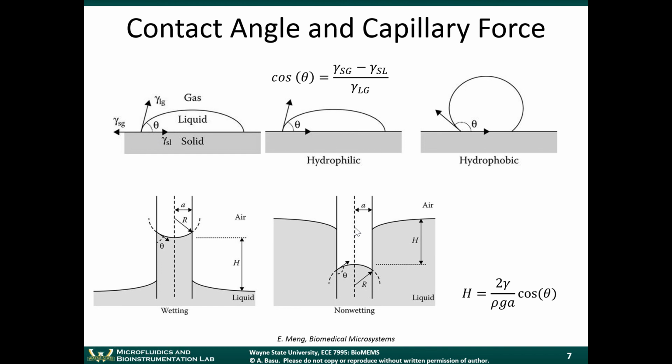Okay, so this goes to show you. Notice that these heights here, the h, it has to do with a at the bottom. Okay, a in this case is just the radius of the capillary. So as the radius of the capillary goes down, these lengths go way up. Right. So it's interesting that you could actually pull... If you have a very thin capillary, the entire capillary could fill completely just by capillarity.